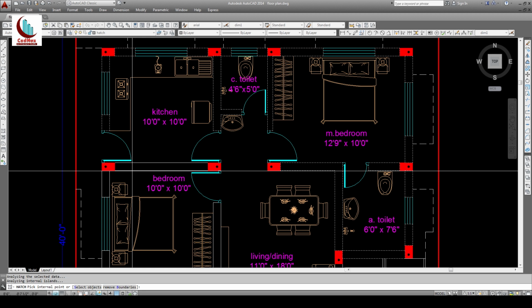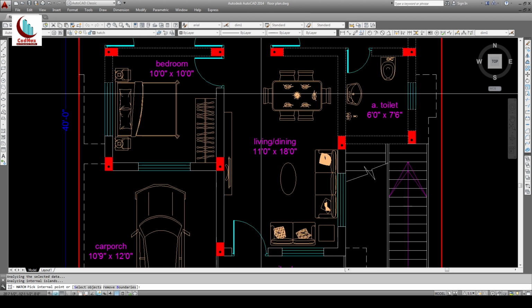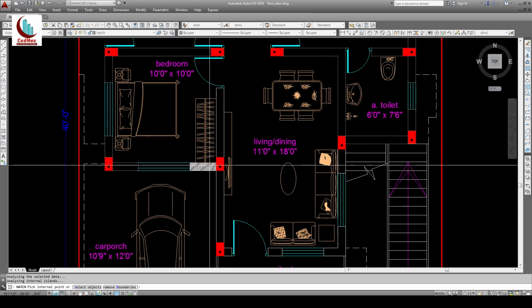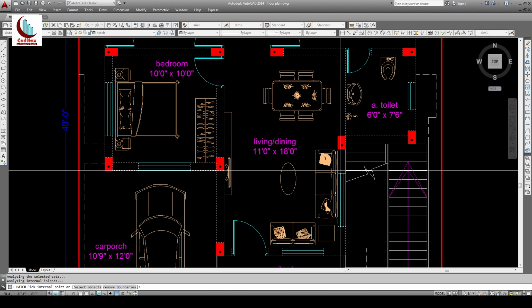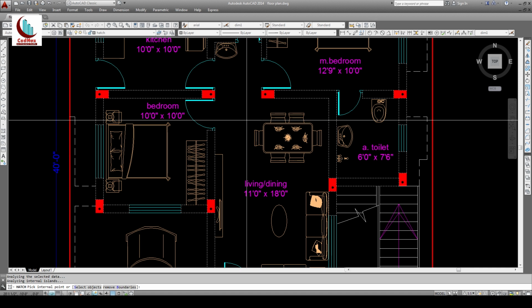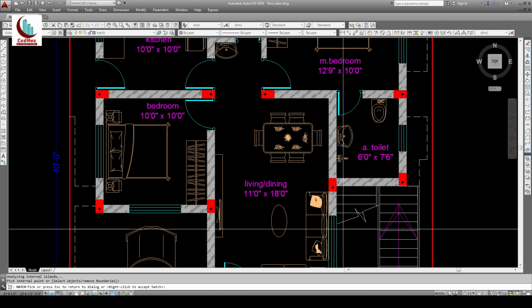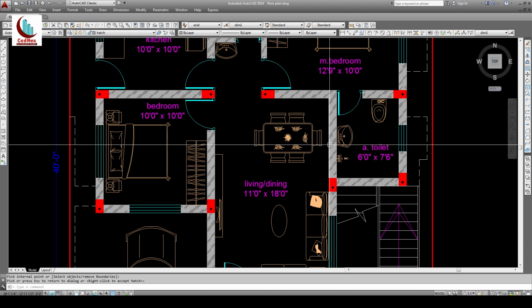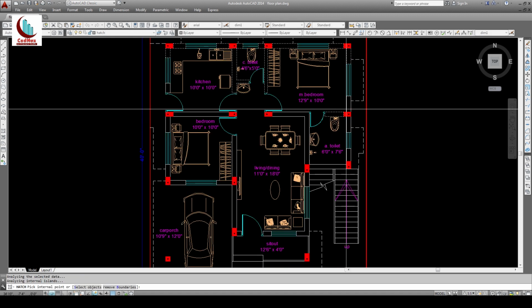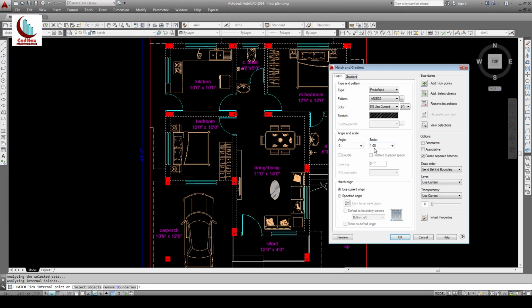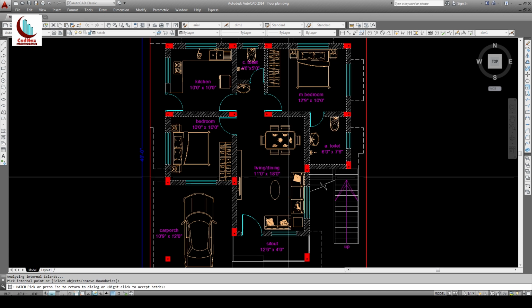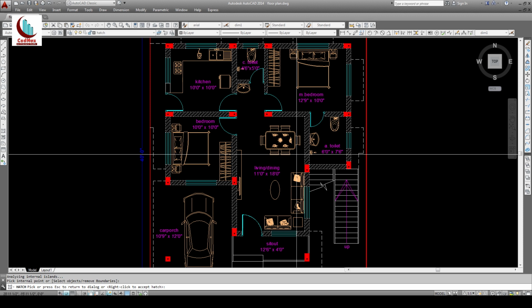okay, fan it slightly up, select this, wherever you want to show the masonry hatch, you can select that. Okay, after selecting, press enter. Now if you see the preview of it, you can see that it's too close. Okay, increase the gap of that. Increase the scale by say 12 and you can see the preview. If it is okay, then you can press enter.